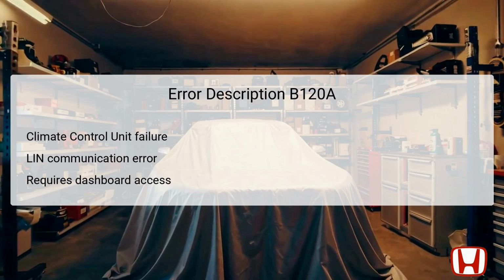The error associated with DTC B120A indicates a failure in the climate control unit, specifically relating to the LIN (Local Interconnect Network) communication bus line. This system is essential for allowing the climate control unit to communicate with the ECU and other vehicle functions. When the communication fails, it disrupts the HVAC (heating, ventilation, air conditioning) operations, such as temperature adjustments and ventilation settings.